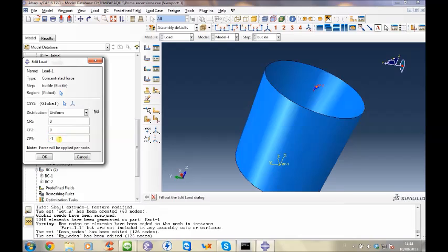If you set another value, you have to multiply your load by the eigenvalues to get the critical load. In this case, if I use 1, the first eigenvalue will be the linear buckle load. So my advice is to always use 1, because it's simple. You do not have to multiply this into your results.